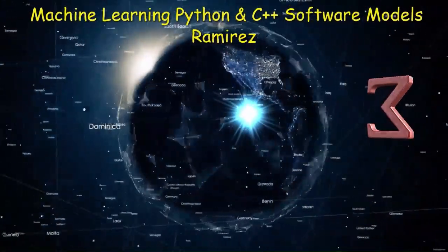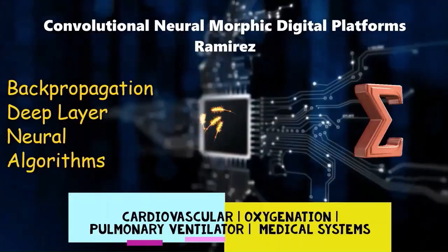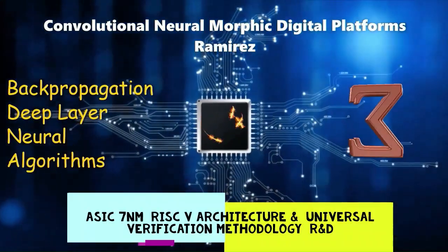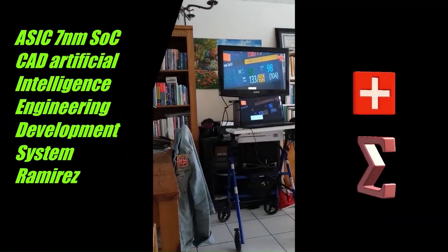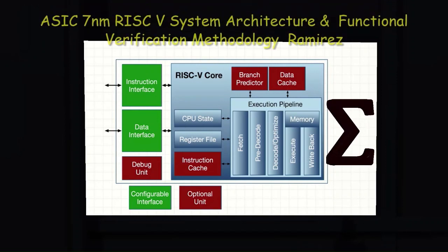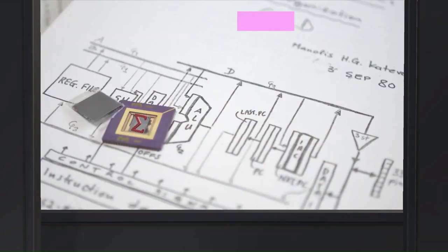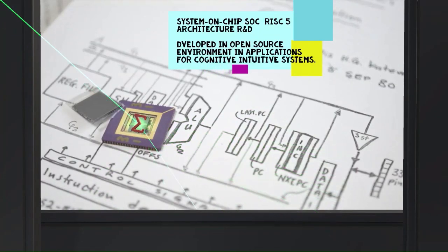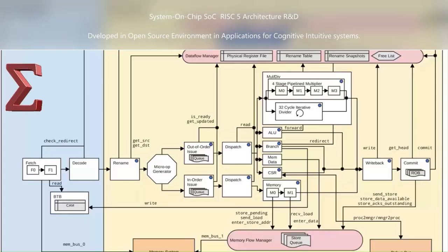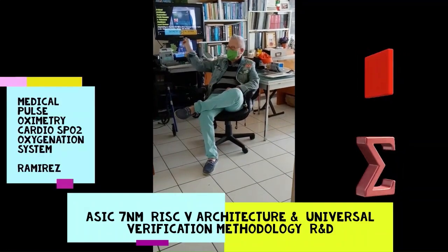The RTL was successfully developed for this ASIC/FPGA system. After functional verification, we also synthesized the unit into a gate-level netlist. Then timing verification was performed to verify that the system-on-chip multi-core system meets timing requirements.